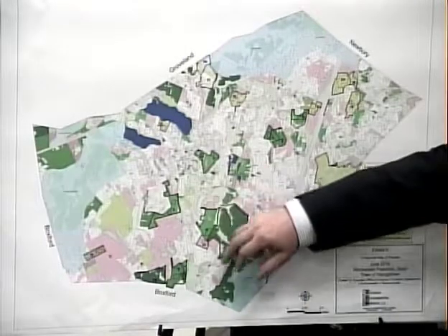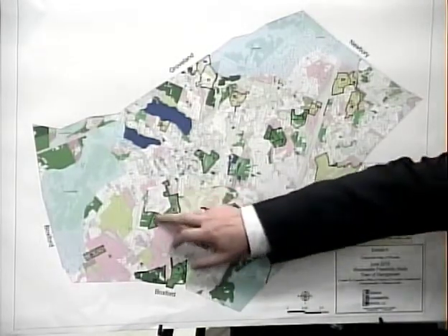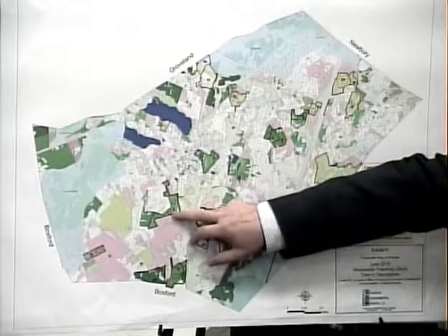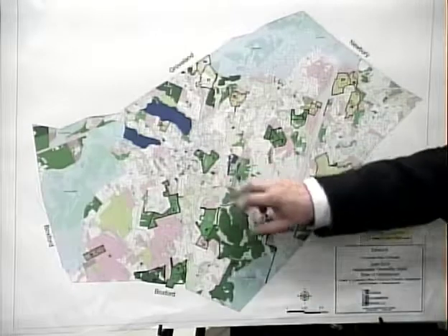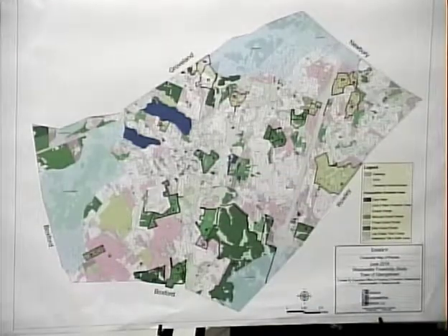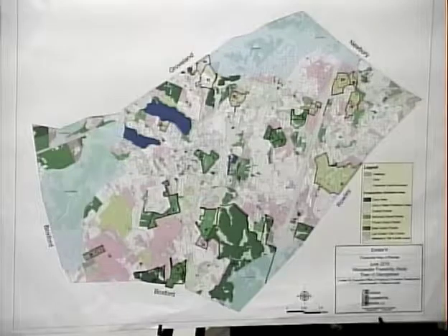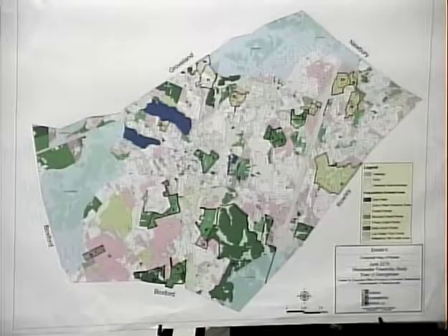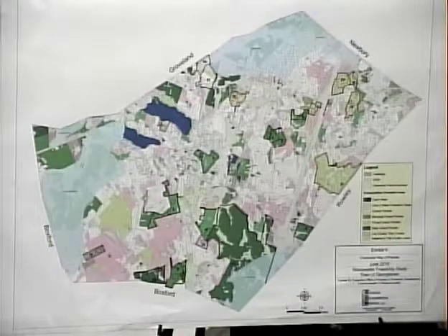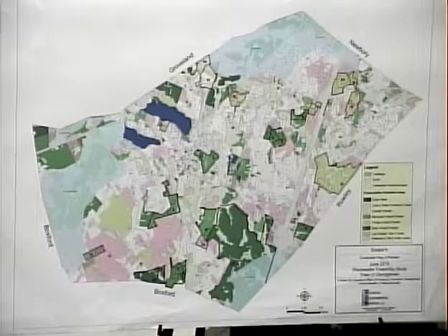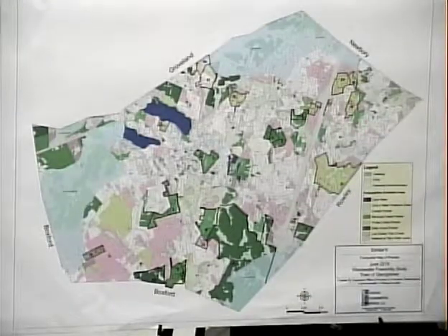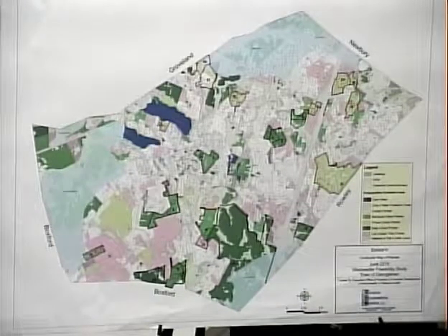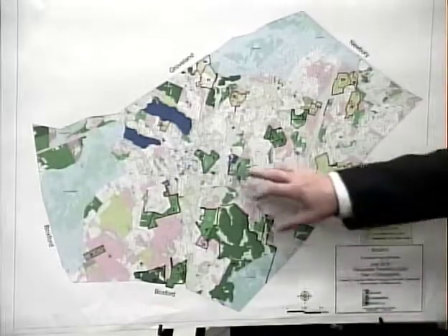So we do have a couple of areas that are fairly close. This one is a primary area that we wanted to look at. These are basically the Pearly School and the high school. There's really not a lot of area on those grounds. Looking at some of the historical records on the Pearly, there's old septic systems, there's new septic systems, so it's fairly limited. It's also within the river area and abutting wetlands. And the groundwater table is fairly shallow as well. So the impacts on the schools, I think, would be significant if we would try to locate something there.